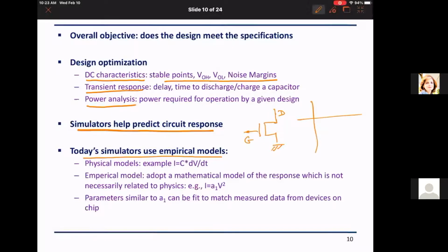So you will get VGS fixed, VDS fixed, and they measure the current I. So they sweep those values. For example, VGS equal 0.8 volt, VDS varied from 0 to 1 volt, and then they repeat with VGS equal 1, VDS varying from 0 to 1, or 0.1 to 1, and they get those points which we have learned before in VDS versus IDS.